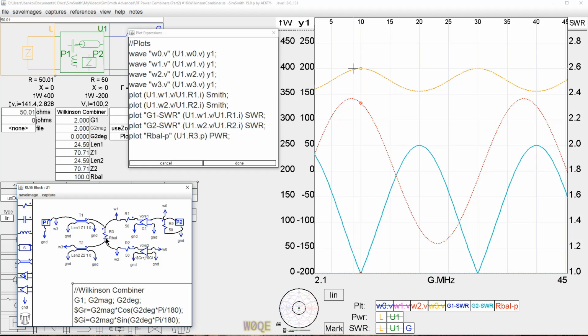As a matter of fact, you might even want to tune this, or you might want to tune the output impedance ever so slightly to really get the balance to be perfect. I've tuned them manually and been able to get this isolation to be down in the order of 65 to 70 dB over the HF range by being really, really careful. Of course, that means then you have to know exactly what this impedance is out here, and it can't vary. But nevertheless, it's doing its job.